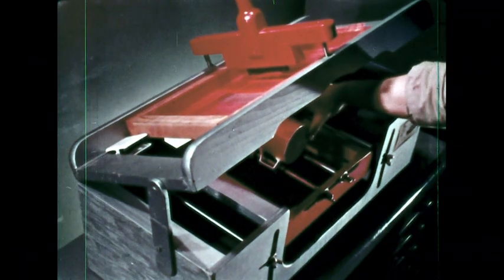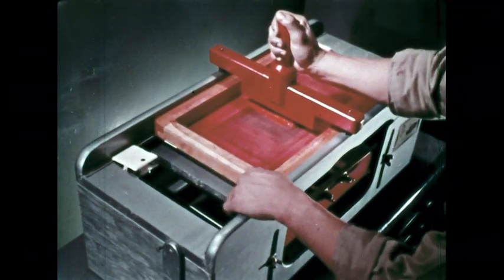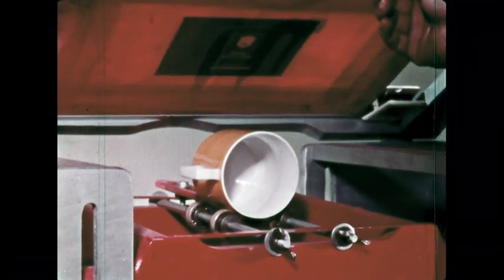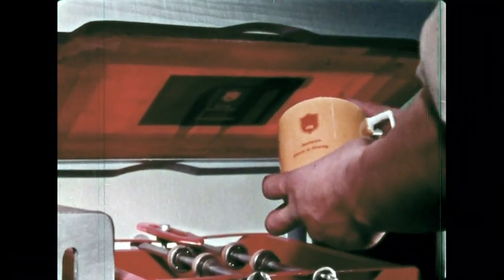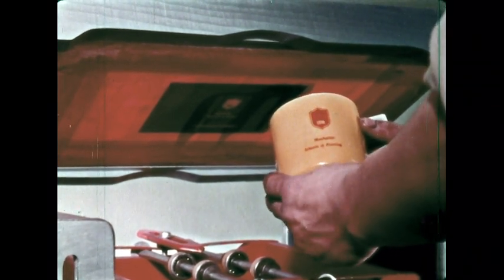But silk screen is widely used for printing on glass and china because it is the only process that requires no pressure to print. This is a good example of how the material to be printed upon will often determine the process which should be used. Printing on metal, such as tin plate for cans, is normally done by the lithographic offset method, because the metal, being hard and unyielding, will more easily accept ink from a soft surface, such as the blanket-covered intermediate cylinder of a lithographic offset press.